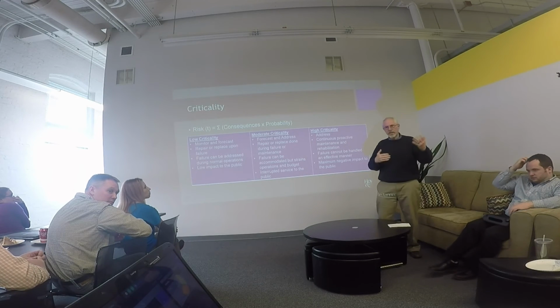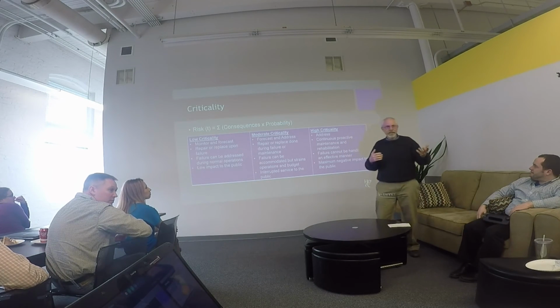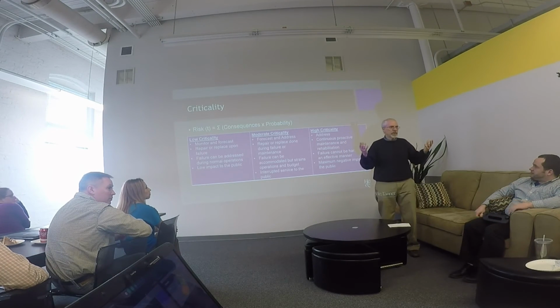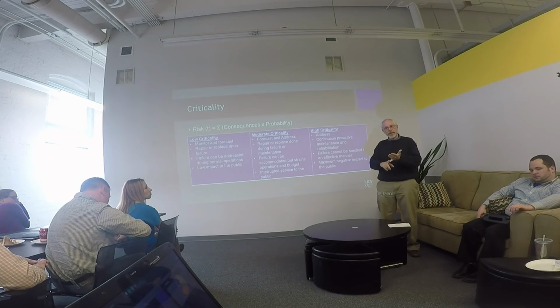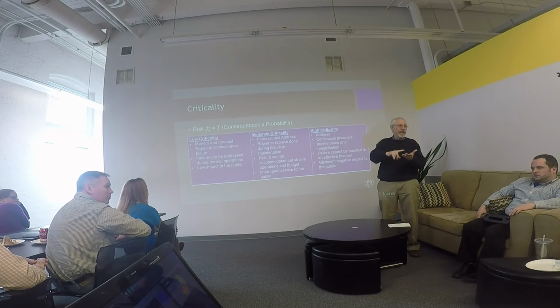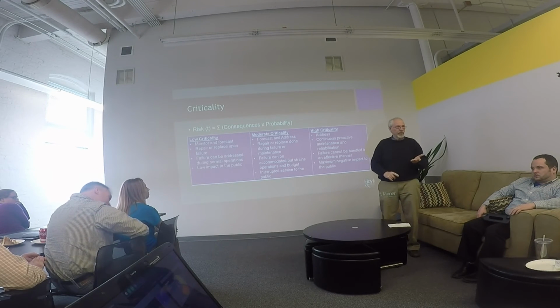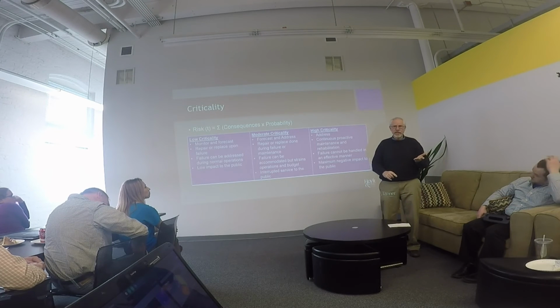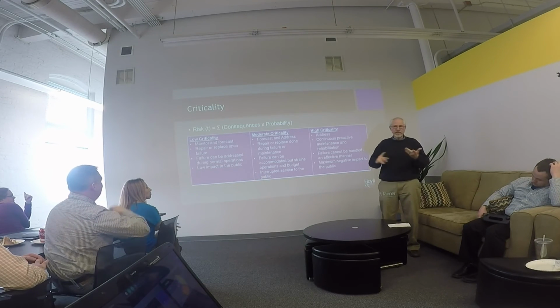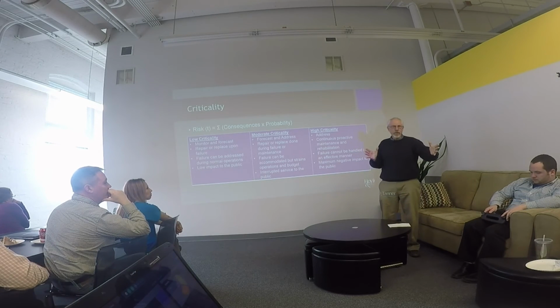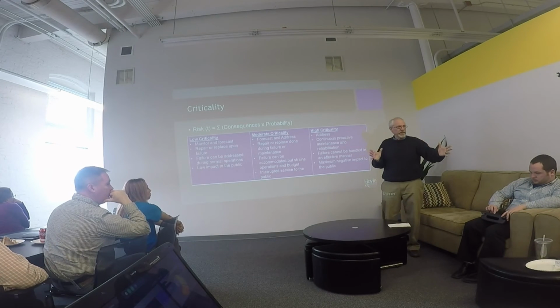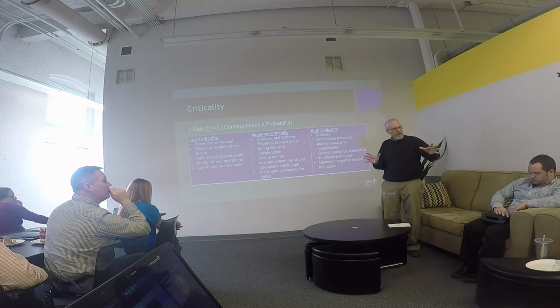When we look at sewer pipes that, like we said, are 100 years old, or water pipes that are 100 years old, and if they're in a development that has low risk, and if it breaks, we can repair it within a day, and we can do it within budget. What do you do? You don't replace it. You let it run to failure. So now you have possibly 40 to 60% of your system that you can run to failure. And that's part of your plan.